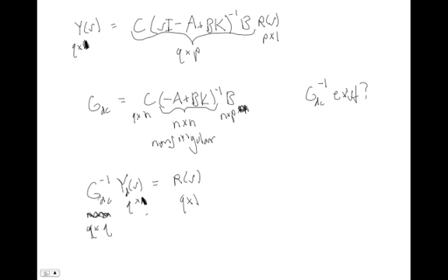But if you're asking well-defined problems, for example, let's say you have a system that's a 2-link robot arm, and your states are the position and velocity of joint 1 and joint 2. It would be reasonable for you to say, I'd like to design a control system where joint 1 goes to 10 degrees and joint 2 goes to 50 degrees. That would be a reasonable request. Think about what your C matrix and your B matrix would look like in these cases. That would be the type of system where you can in fact get an invertible G matrix, and this algorithm would work.